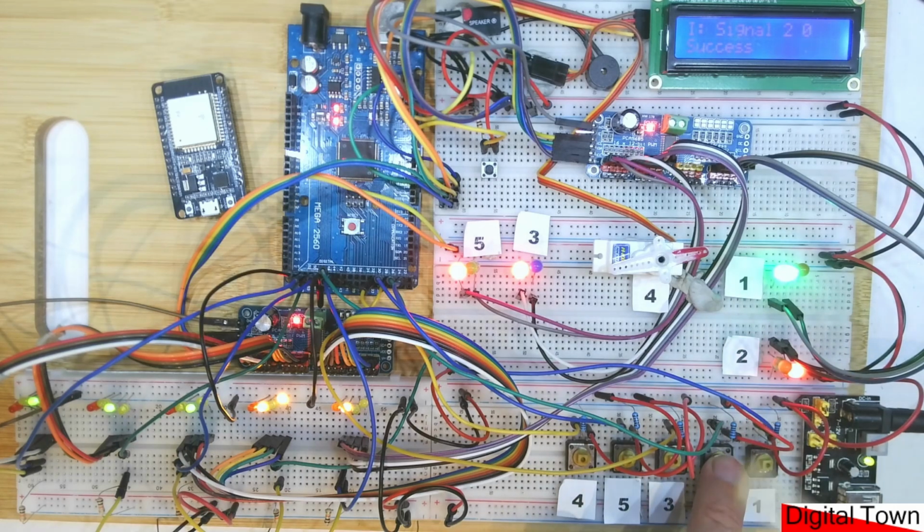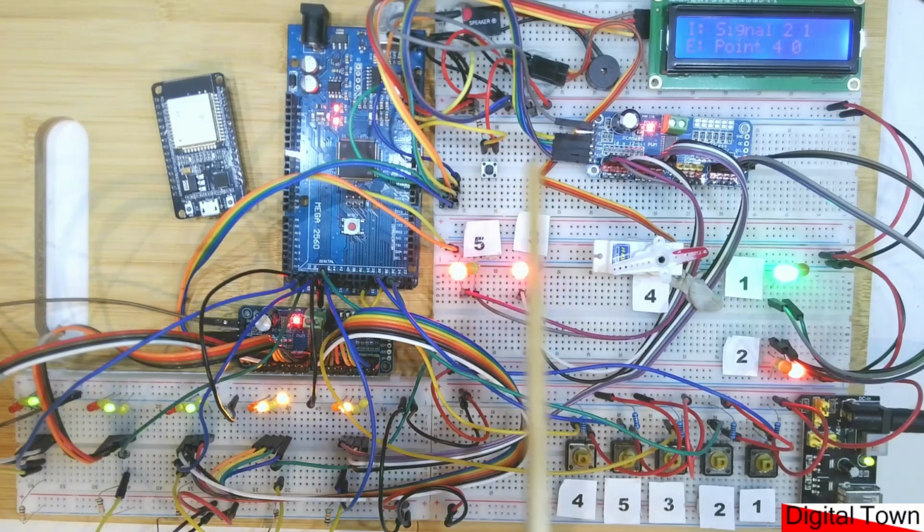So I'm going to turn signal 2 off. Now if I press the button, I get the alarm, but you'll notice the LED doesn't change this time. So full interlock mode stops something actually working, whereas the trainee mode will sound an alarm, but will allow you to still continue. The reason for trainee mode is if you've got a layout and you just want to move some stock from one end to the other, if you've got to set all the signals every time you want to move a turnout, it might just drive you mad. So you can turn it into trainee mode and just move things around just with the annoying beep.